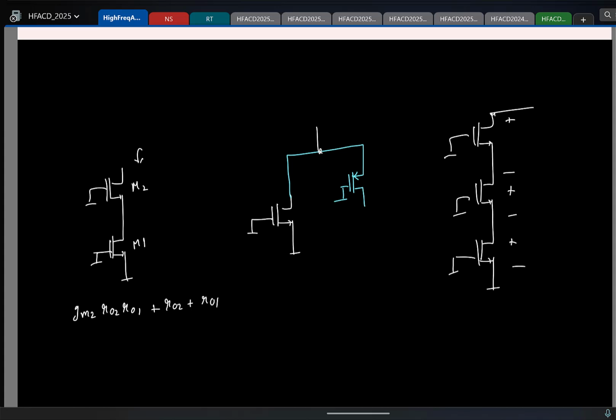So we saw gain boosted cascode as an alternative technique. The idea there was you have the normal cascode, and you make sure that the drain voltage here does not change a lot. So you actually give it to an amplifier. With respect to small signals, this is what was happening, and this was the gain boosted cascode.